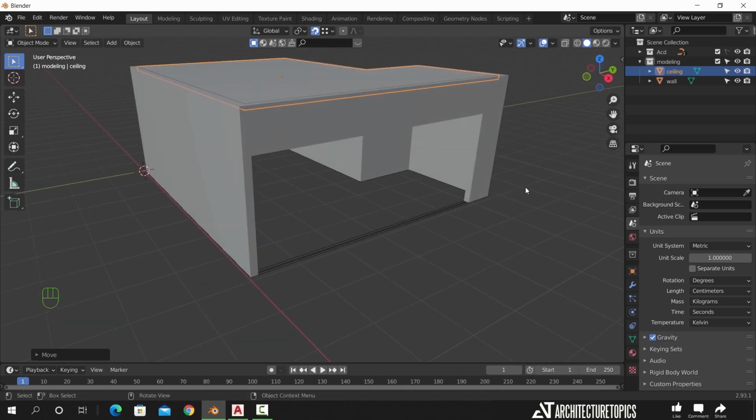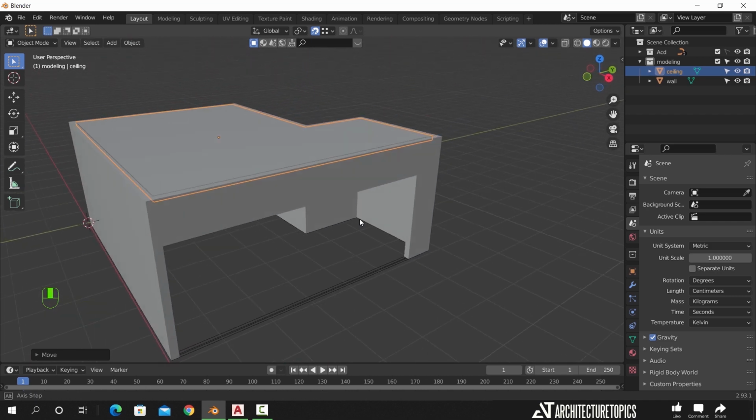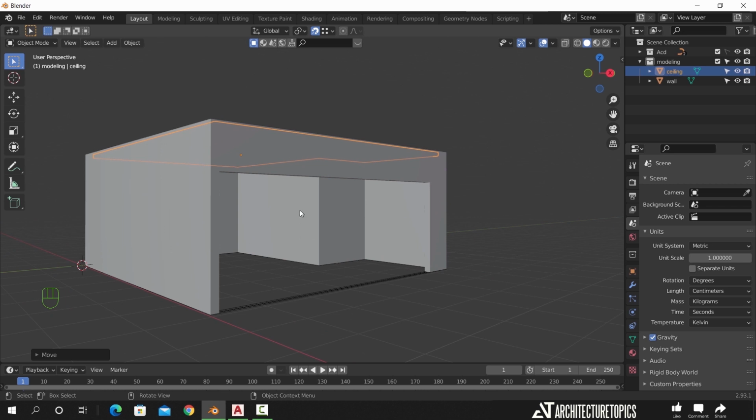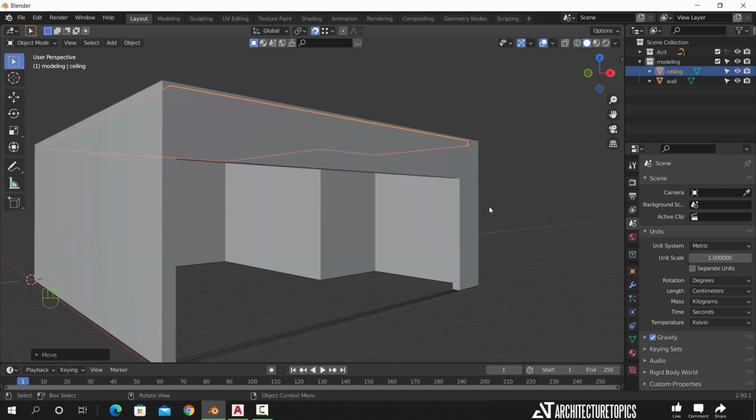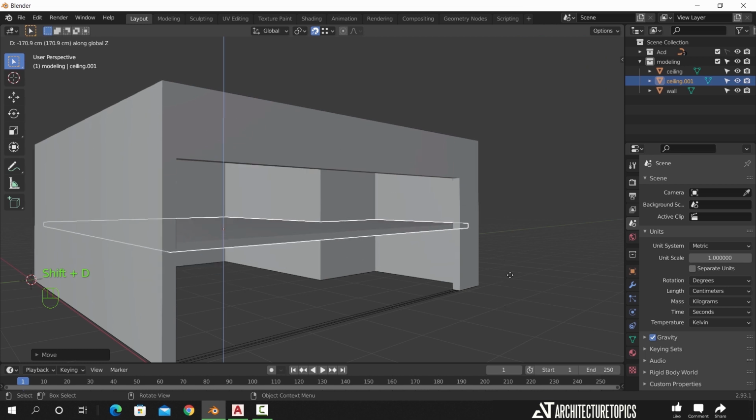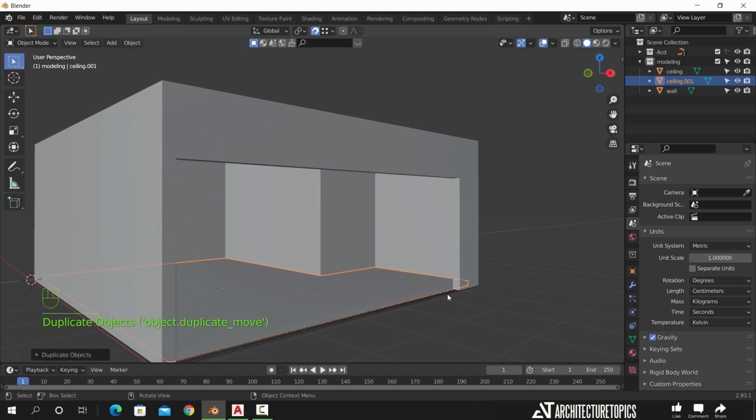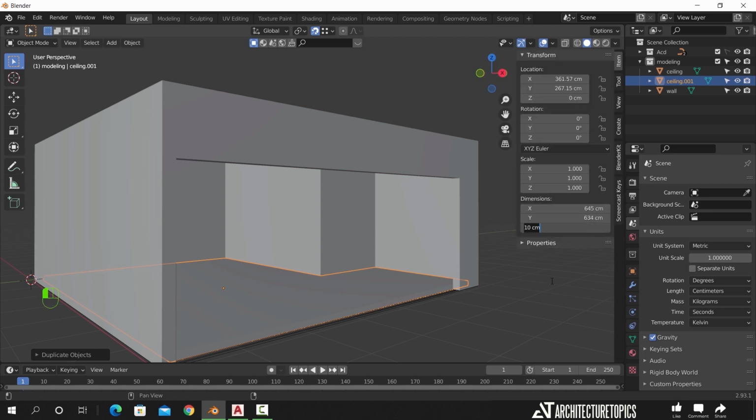And that's for the top ceiling. We do need a copy of this to work as a bottom ceiling for the hidden lights, curtains and other wire connections, so hit Shift D to copy it. Change the thickness to 5, and put it on a height of 270.